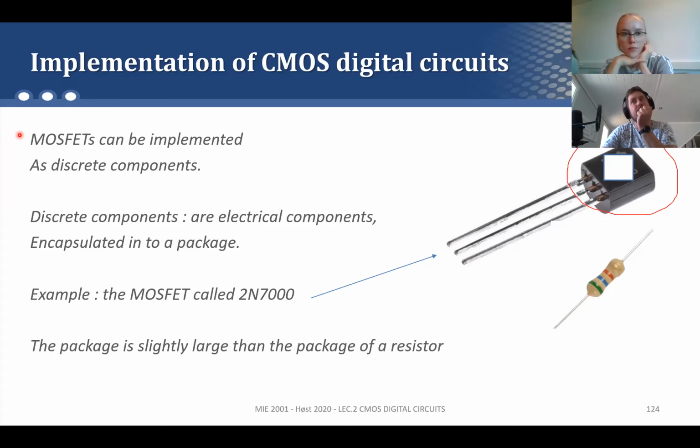And this in some way goes in contradiction with what I told you at the very beginning of the last class, where I told you that the PMOS bulk is connected to VDD, and instead the bulk of the NMOS is connected to the ground. It's always like that nowadays. But in the past, this is because today we electronic engineers mainly design circuits with MOSFETs in integrated circuits, in ASIC, so in microelectronic circuits.